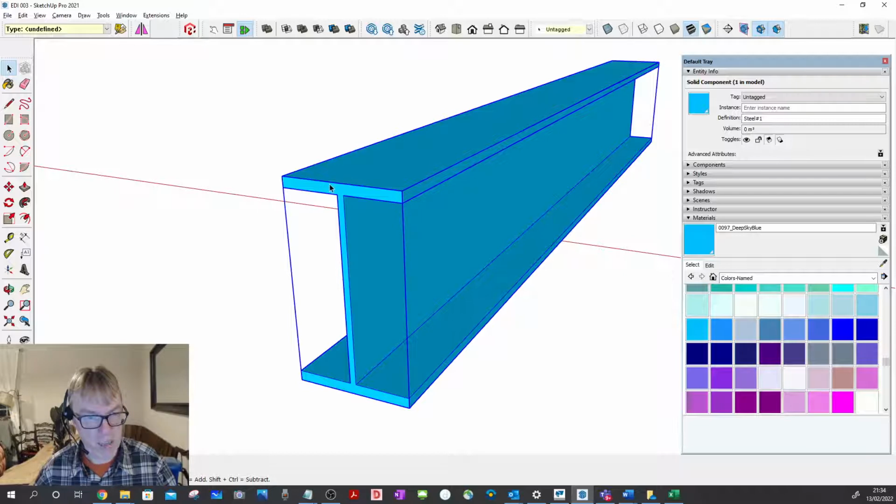Now, at this point, I want to give this object a name, and this is quite important. So it has to be a unique name. We have a format defined, so I'll demonstrate that just now. Within this, there's 1, 2, 3, 4, 5, 6 elements in the code. The first element would be the project or the building number. This could be 1301 in my example, underscore.